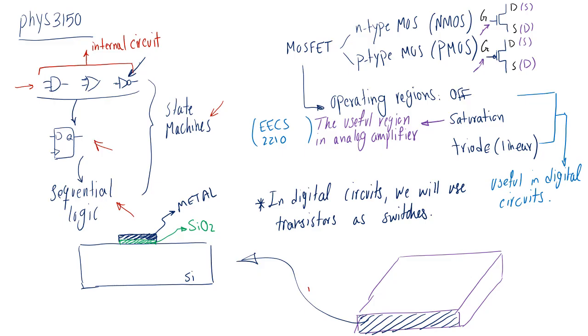Anyway, if you take a silicon substrate and we put this insulator, so let's call this insulator here, and then a metal on top of that, and then using a process called diffusion, we grow two conductive sections inside the silicon. So this is basically conducting.